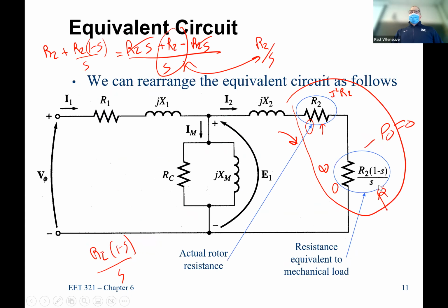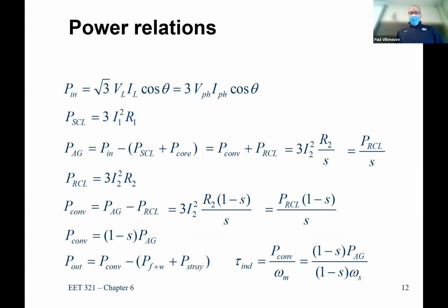Right here. If this is the rotor copper loss, this is I squared times R. The I squared gets square rooted. This just multiplies it out front. So we're just multiplying it by (1 minus S) over S. So that's exactly what we expect. Take the rotor copper loss, multiply by (1 minus S), we have that value.